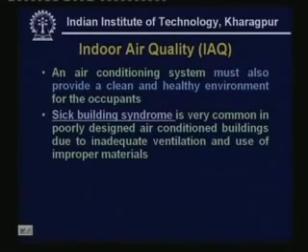As I mentioned, sick building syndrome is very common especially in places where the outside air is dirty, and the designer of the air conditioning system provides very little ventilation to save energy. Typically the indoor air quality depends on the amount of ventilation that is provided, the quality of the outside or fresh air that you are supplying, and also the kind of materials you are using inside the conditioned space.